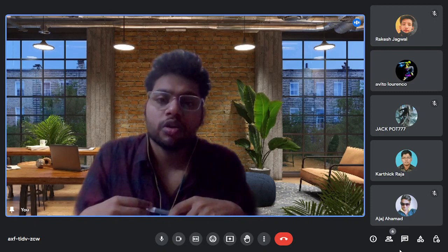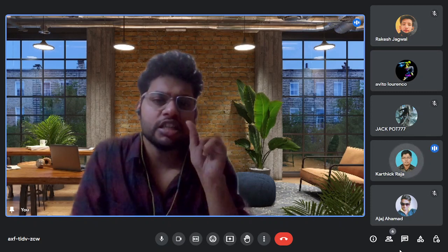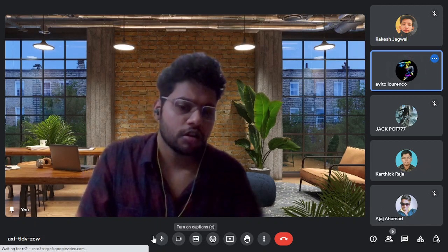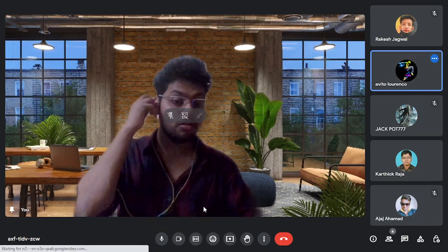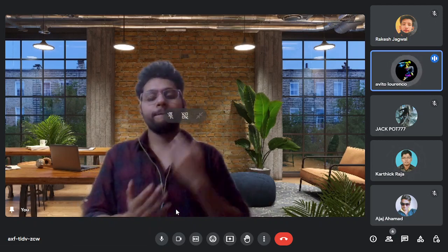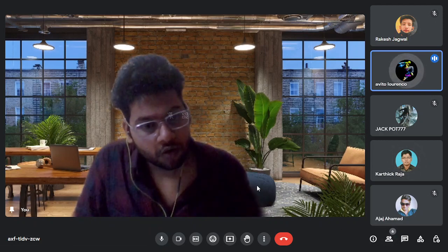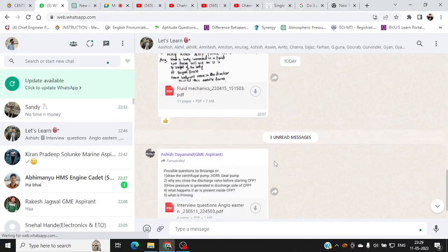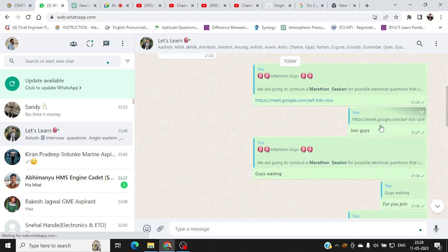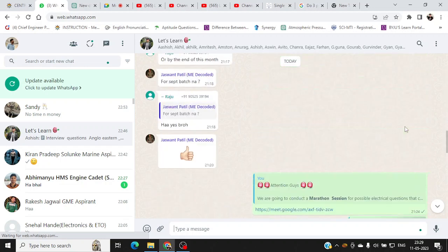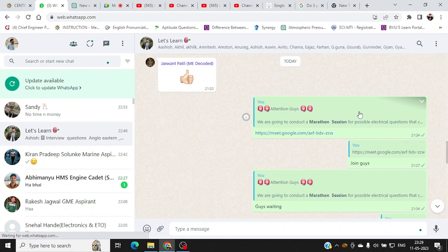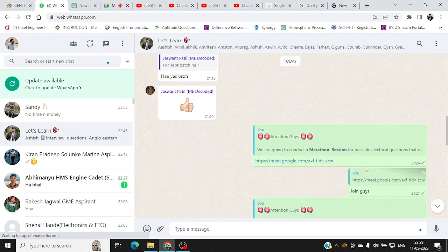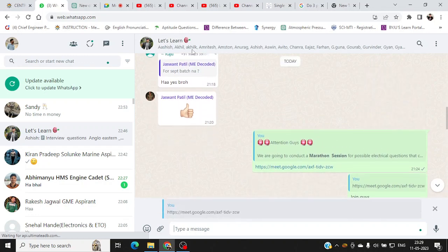No, the galvanometer is used to measure small currents, to show the direction in which current is flowing. The needle moves towards the right side, meaning that is the direction in which current is passing. If it goes to the left side, that is the direction in which current is passing. Now, when is the Wheatstone bridge balanced? When there is no current passing through that middle line. So we have to keep checking our unknown resistance until we get a balanced Wheatstone bridge.